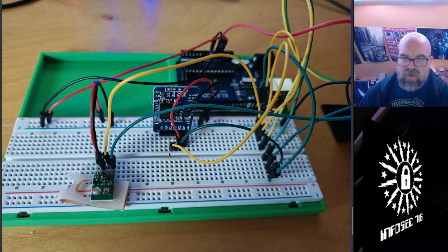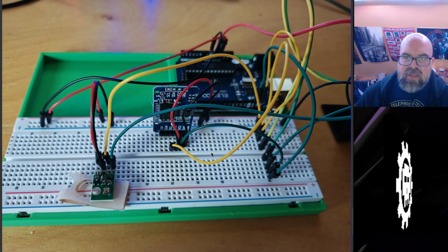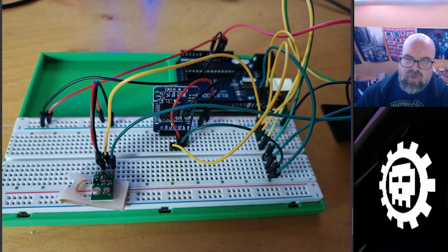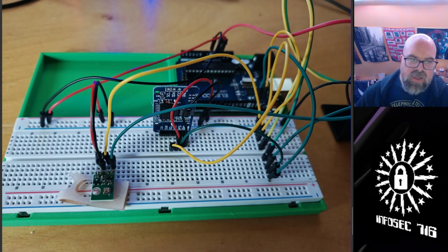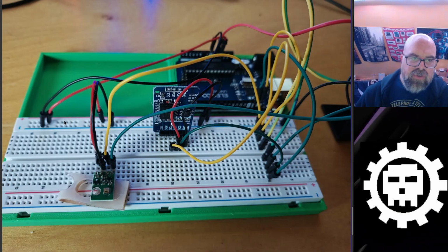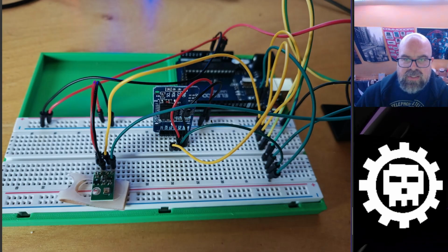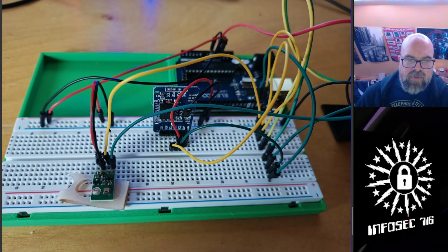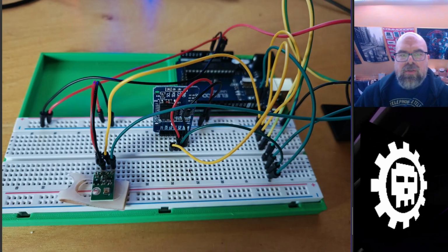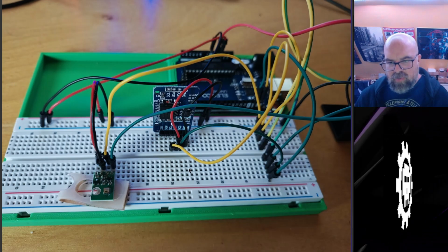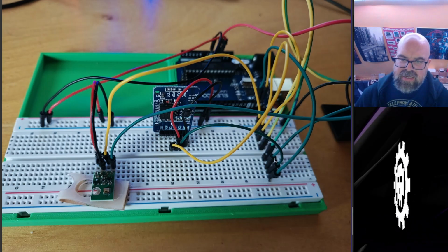If we zoom in a little bit, right, we'll see exactly what we were talking about. We've got the yellow clock wire, the green data wire coming over here to this row of tie points, and then our devices wired in line. Each of these are being powered off of this 3.3 volt rail. You can see that here, you can see that here, and they're both being grounded back to this ground rail. So we have 3 I2C devices all connected to the Arduino at the same time via these clock and datas.